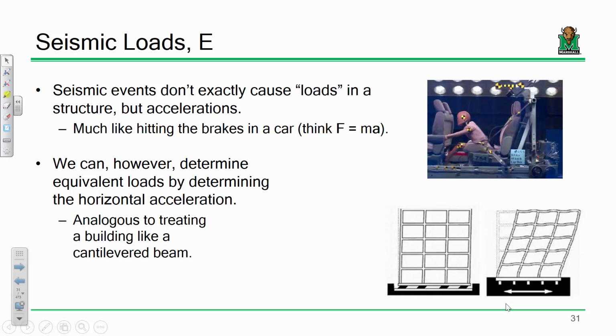These are extreme events. In the world of structural engineering, there's a term called extreme events. And extreme events are just that: events that are somewhat rare and that don't happen throughout the day-to-day performance of a structure. An earthquake is one of them. So let's say we were designing a bridge, and we were looking at the pier of the bridge. One extreme event would be an earthquake. Another extreme event might be a collision, like a boat or an ice collision into the pier. That's not something that happens all the time, but it can happen, right? So those are extreme events.